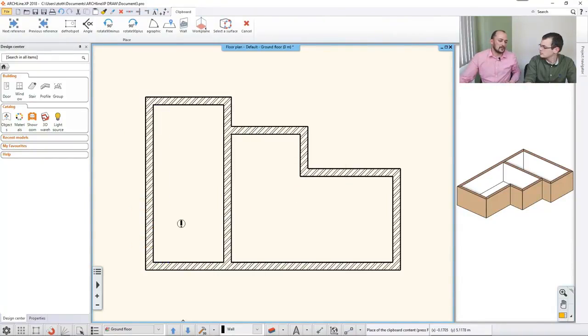See, now it's important that when you hold your mouse at a point where it makes no sense to place this shape, because it's not in a wall, then you will see this exclamation mark. Just don't worry, that means that you cannot do that here. But if you move your mouse over the wall, then you can just move it somewhere. And again, here you can use the F5 key to cycle through the top point, the center point and the bottom point, as you can see here. So now I know that this distance is 2.3, I type it and now I have that.